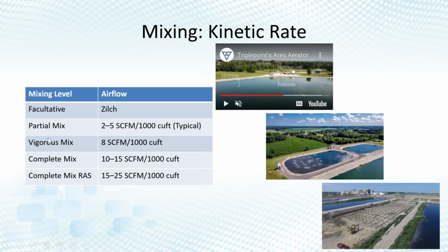The next big jump is actually complete mix, which means every piece of solid that comes into your wastewater lagoon is kept in suspension at all times. So it's always there. Bugs are eating it. There's oxygen all around. We're going to get really, really quick treatment. And the air we're putting in is multiple times more than that partial mix.